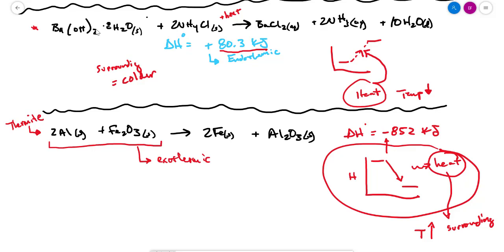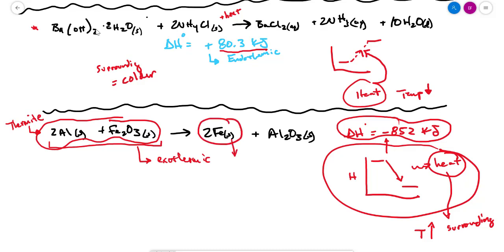So instead of having to bring out a huge torch to heat up something with, say, acetylene and oxygen into a remote place, what they can do is just carry a whole bucket full of aluminum powder and rust, and they can drive this thermite reaction, which gets so hot based on this enthalpy change. It's so hot that it produces liquid iron. And so you essentially have on-demand liquid iron, which is exactly what you need to weld railroad tracks together. So I'll show you a YouTube video of that, hopefully later in this chapter.